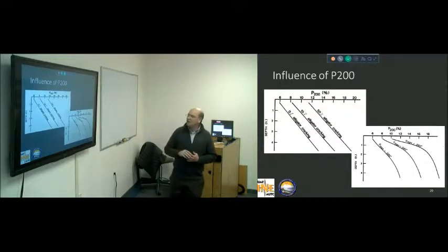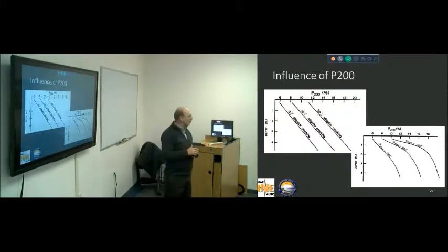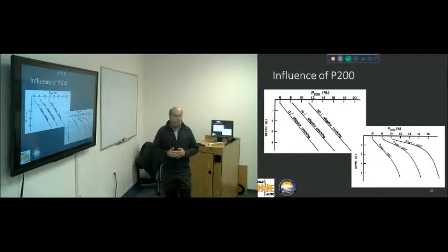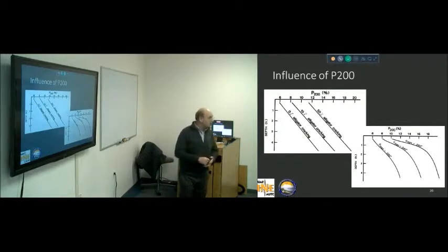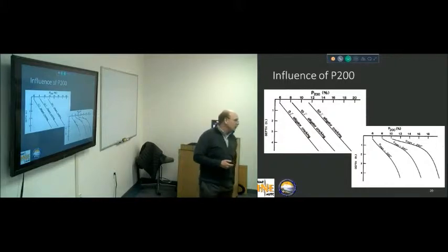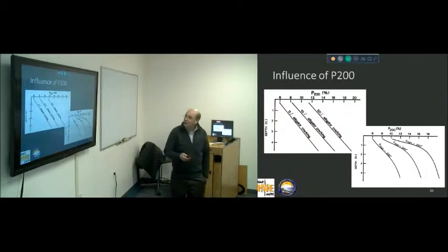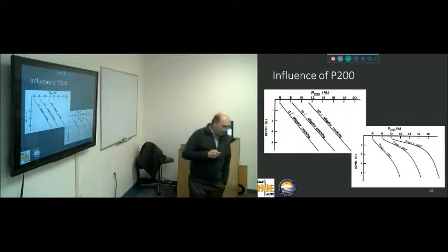But again, we can see that as we get deeper into the soil, we can allow more fines without hurting the performance of our pavement, which is consistent with what we know from our equations for stresses and strains. As we move down, the stresses go down, we can allow the use of a weaker material, and consequently more deflection at those layers. And so that's more fines as we move downward, which is something for us to remember.